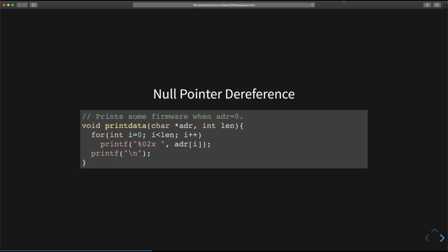Meaning that when you dereference a null pointer, you get the beginning of your code. So if you can ever find a place, either in the application or in the bootloader, where you can trick it into sending you data from the device's own memory at address 0, you have a firmware dump.